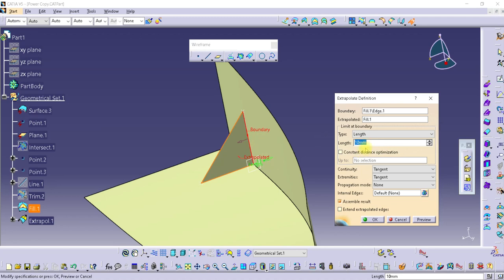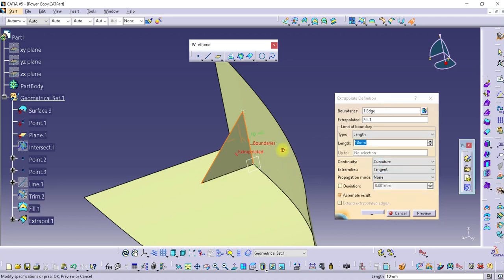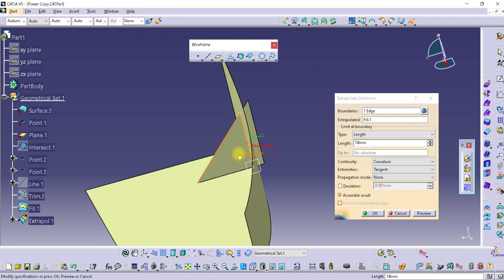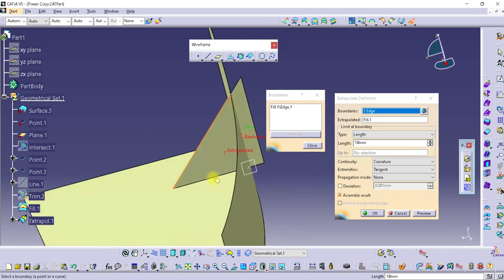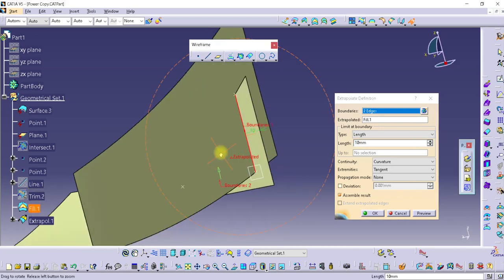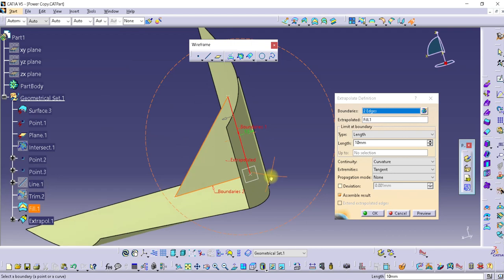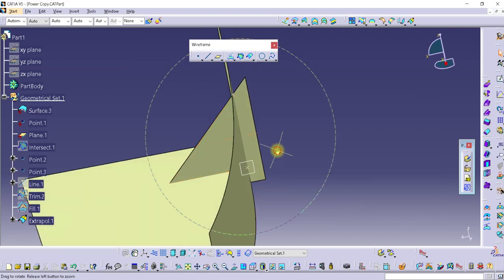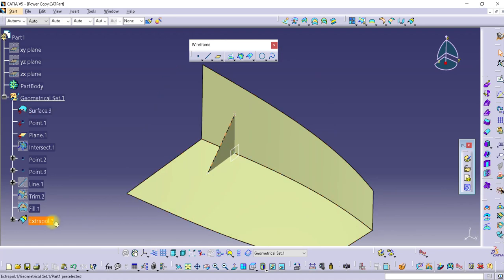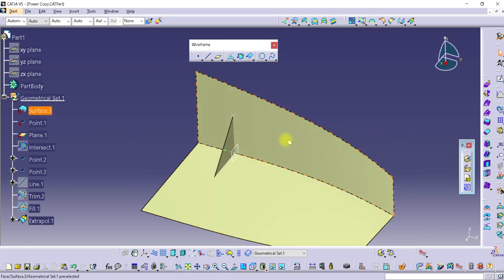Extend 10 mm curvature, for example. We need to make sure we have more surface, it's better. So then I extend here, making sure everything is 100% intersecting. This is the next step to do, extrapolate to make sure everything is 100% touching the limit surface.